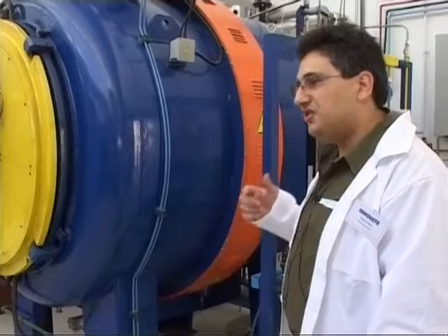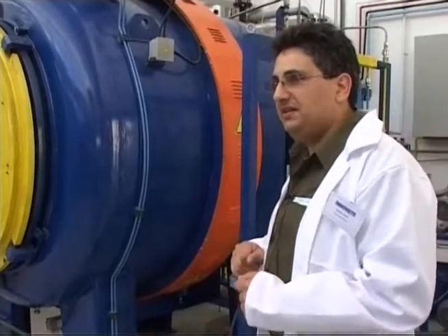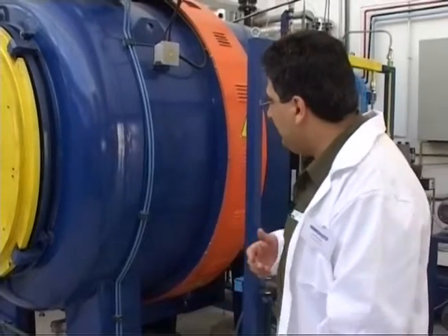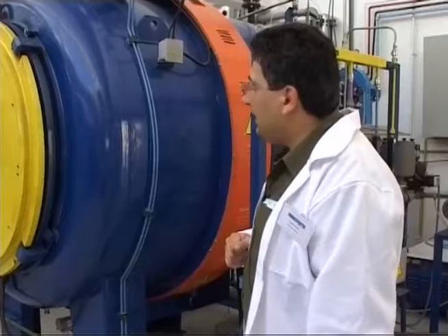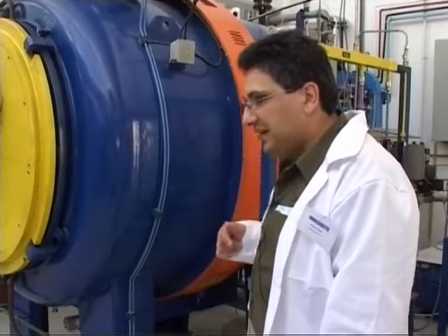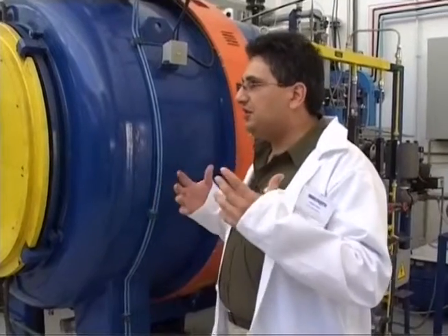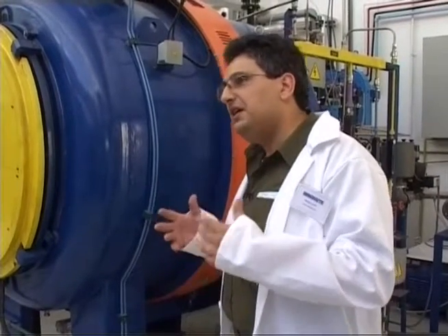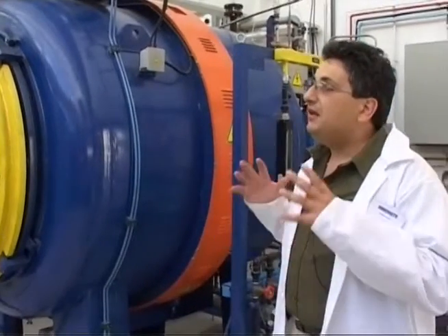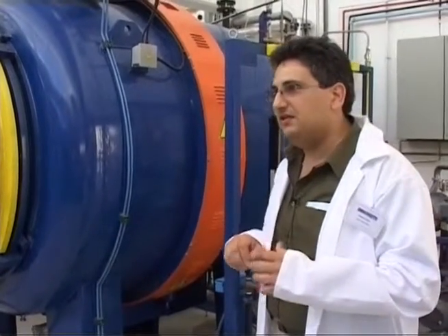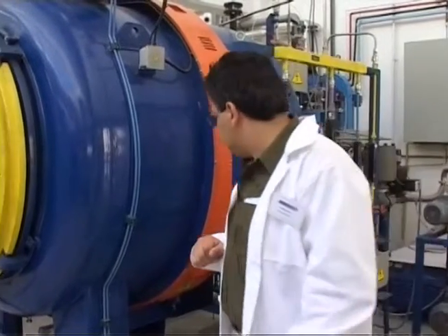Plasma nitriding, which is a physical process which in the end obtains the same effect as gas nitriding but in a cleaner way. And both gas and plasma carbonitriding of the components. Now, nitriding is the introduction of nitrogen in the surface in order to form nitrides in the surface layer and pin the dislocations of the surface, making the surface harder and more wear resistant.